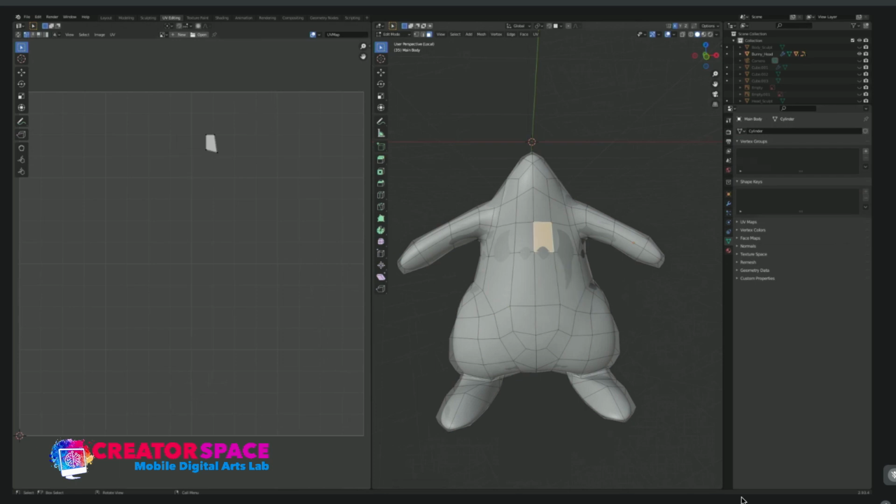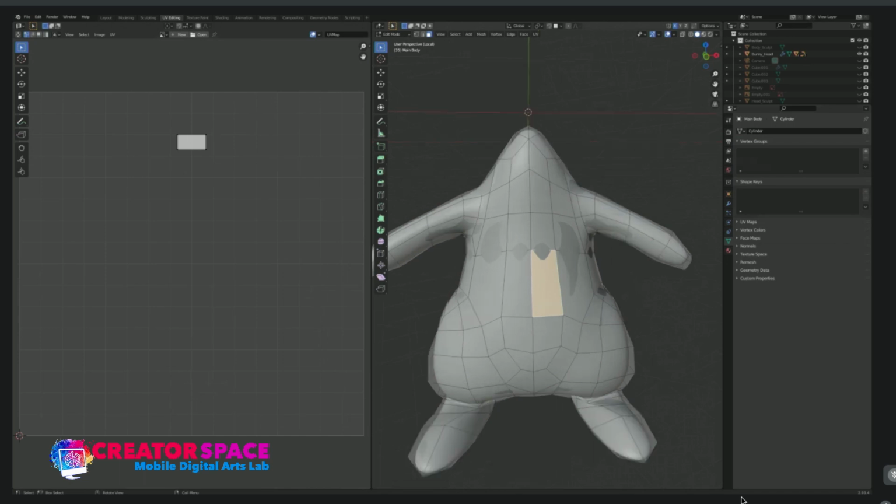For whatever reason, when you're doing the modeling, like the topology, it's actually flipped, right? So the inside of the face is flipped, and you see the inside of the face on the outside, and that can cause problems. So that's why you have to make sure that the proper face is looking outside, right? That's what you need to do.